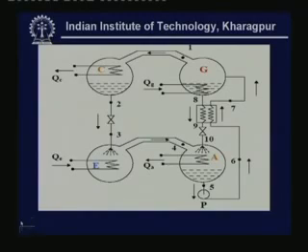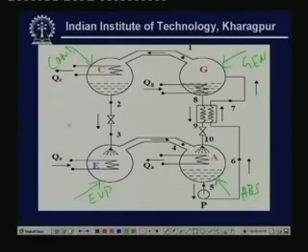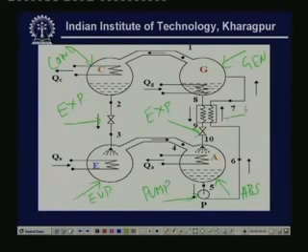Now, I have already explained this while discussing vapour absorption refrigeration systems, but let me once again quickly explain the system and show the various state points. As you know, we have the evaporator here, this is the absorber, this is the generator and this is the condenser. In addition, you have the expansion device for the refrigerant and you have the expansion device for the solution, you have the pump for solution and this is solution heat exchanger.